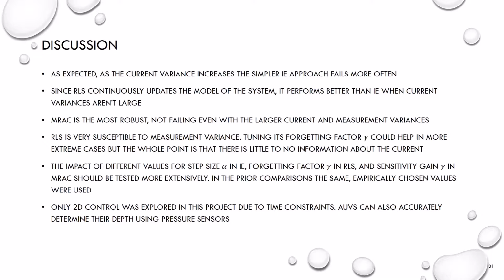For all of the tests done, the same parameters were used for all the different approaches, and these values were all obtained empirically through trial and error in the simulator. Once again, only 2D control was explored in this project due to time constraints, and once again, AUVs can quite accurately determine their depth using pressure sensors, so controlling the Z direction was not a big concern, at least not in this project.